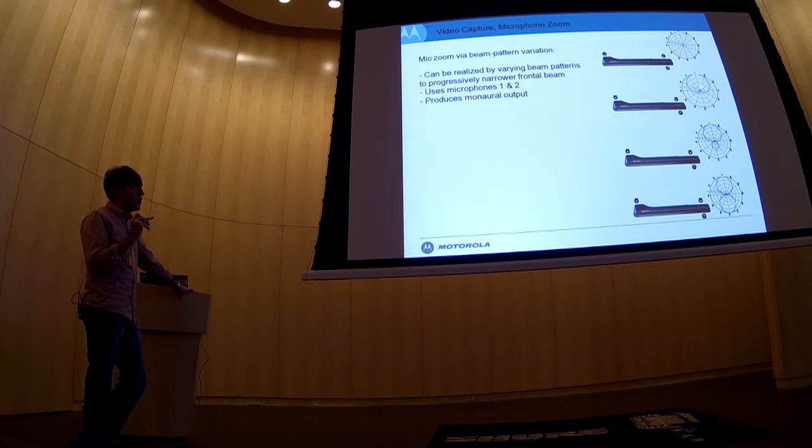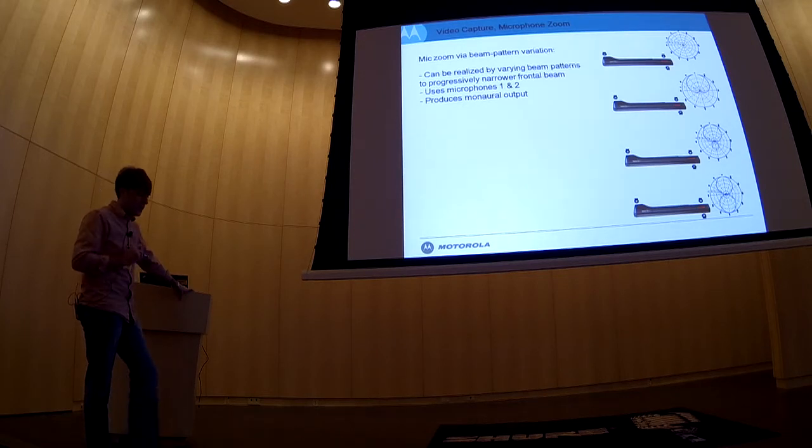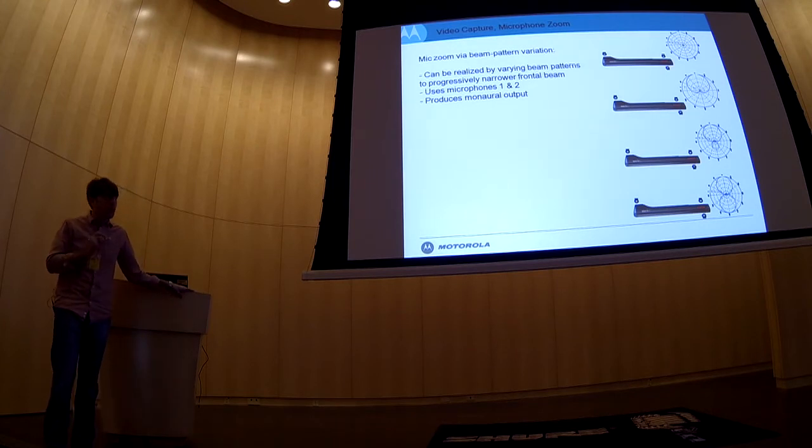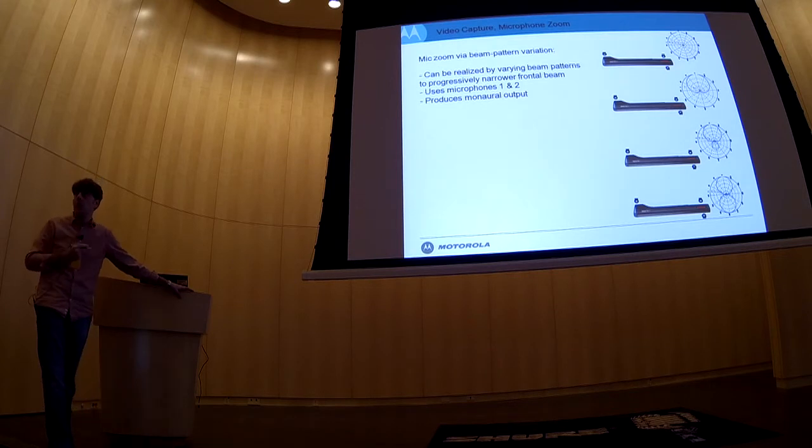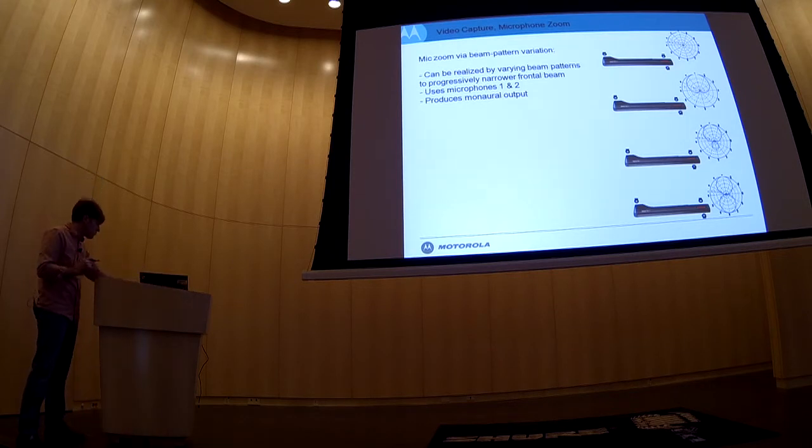As we vary that pattern from cardioid through hypercardioid, dipole, inverse hypercardioid, inverse cardioid, we will effectively reduce the width of the audio that we're picking up in the direction of where the subject will happen to be.